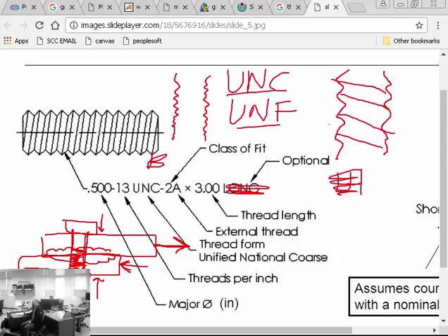In an ideal theoretical world, we want this right at that breaking point, because that means we're getting the absolute most friction value we can, and the bolt's not doing that much. But obviously we have a safety factor. We don't want you to tighten them that tight, because what eventually happens? They just shear apart, and then you lose everything. But when they're tightened down, that friction becomes so strong that the bolt's technically not doing much in terms of resisting across its shear plane. So a little thing to keep in mind there.